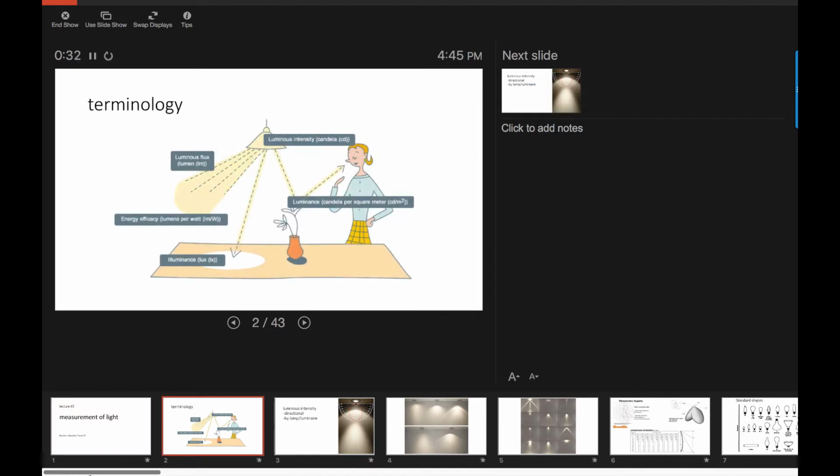And there's a couple of terms that you really have to nail before you can get the exact sense of what we're doing here. The biggest thing, we talked a little bit about luminous flux. That's the number of lumens that come out of a light bulb, a lamp. And that's usually printed on the box. It's actually required by law for light bulbs, again, measured in lumens. There is another element of light sources called luminous intensity, and that's light flowing in a specific direction.